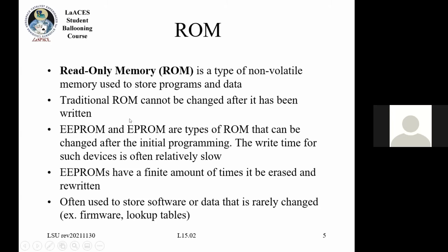Usually that sort of thing is relatively slow, and there is a finite number of write cycles because of how these work. So usually what those are going to be used for is data that you're not going to change often. You can have something called a lookup table, where you give it a number and it returns another number. There's a bunch of fixed numbers that I don't have to change. That may be where the firmware that starts up your device will be.